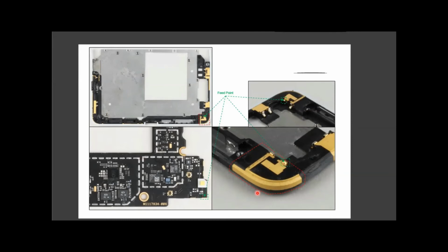One is doing the receive MIMO part of LTE. The other radio connected to this is doing Wi-Fi at the same time. And that's one way of reducing the number of antennas in the device: using an antenna sharing concept. Again, this is another coupled element, if you look at it.